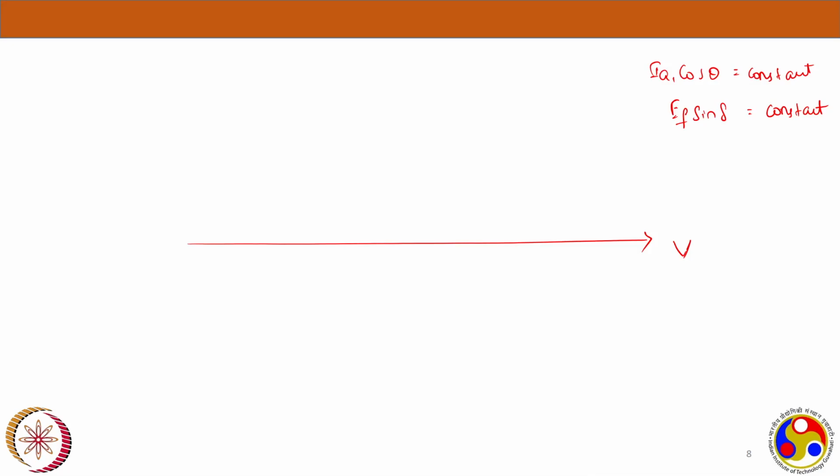Let's say I am drawing IA1, this is theta 1. It is a lagging power factor. Now with IA1, I can get the IA XS drop, which will be perpendicular to it. But I have to subtract this, minus jIA XS, from V to get the excitation voltage.